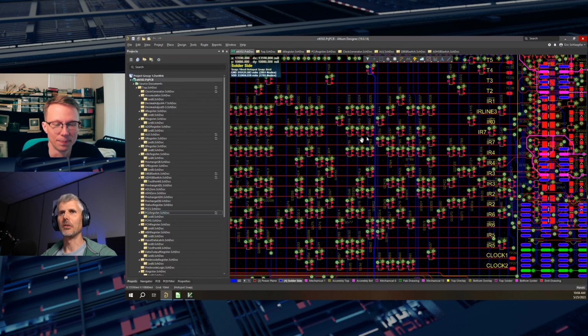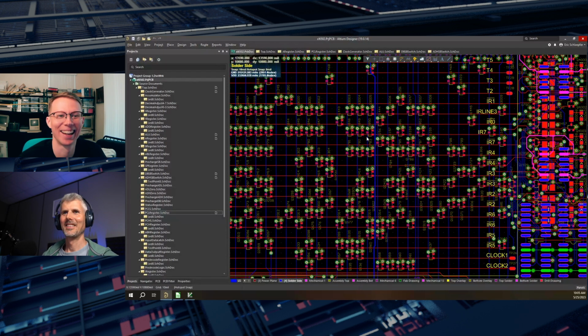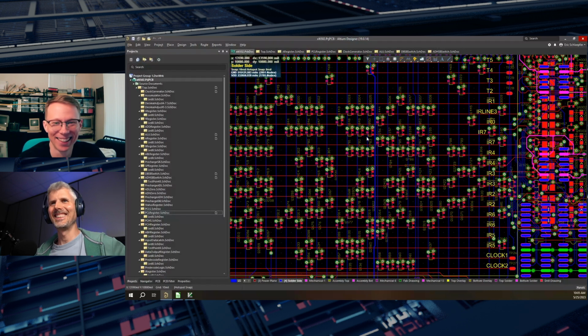So you've done the layout. I guess the board is pretty big, but you probably didn't have to go to a special fab place to get that made, did you? Most fabs can do a board this big. It's just expensive. The other challenge was the assembly. The pick and place required several reels of the same part. Did you do that yourself? No, I didn't do this by hand. That would have been tedious. Although I did swap out the LEDs when the boards came back because they had used the wrong part number, and that was definitely tedious.